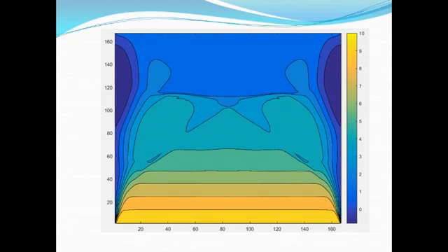This is a contour plot of u velocity with the source, or u1, at the bottom of the screen, and the channel mouth, or u end, at the top. Also taken at time step 10,000, the velocity clearly drops off quickly in the region where the height increases suddenly at about x equals 50.